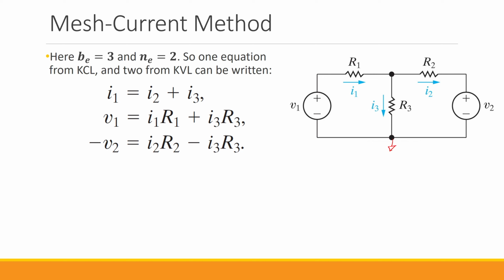If I consider this to be the reference node, and let's just say I call this node 1 and I assign V1 here, what I can write is simply the KCL for all the exiting currents from node 1 like this. So let me just call this Vn and I call this node n, so there is no confusion.